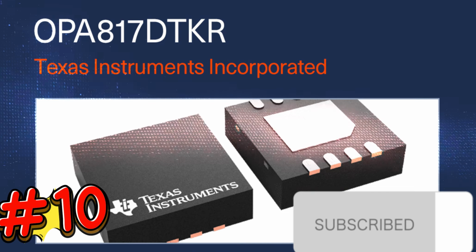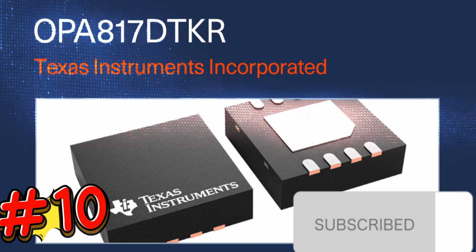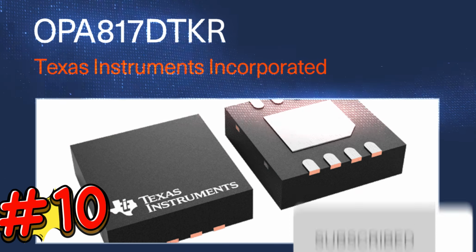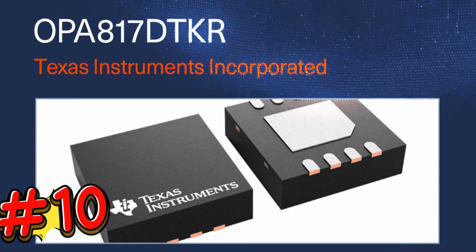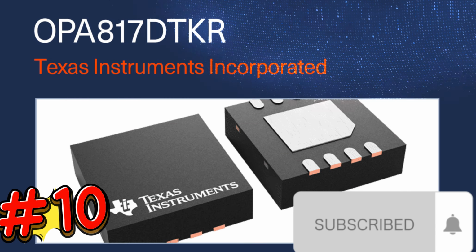Equipped with a low noise junction field effect transistor, or JFET, input stage, the OPA817 features a wide gain bandwidth of 400 MHz and a supply range from 6 volts to 12.6 volts. The fast slew rate of 100 volts per microsecond allows a wide large signal bandwidth and low distortion when used as a high impedance buffer in high-speed digitizers, active probes, and other test and measuring applications.